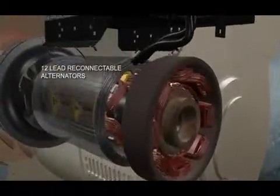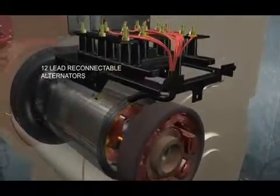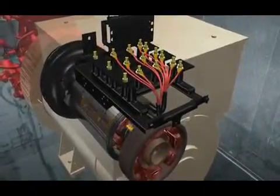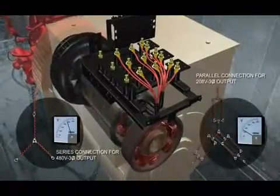Doosan mobile generators also include alternators with 6 coils wound into the stator. This provides 3 voltage sources or phases. Because each phase combines 2 coils of wire, the sources can be connected in series for high voltage applications or in parallel for low voltage needs.